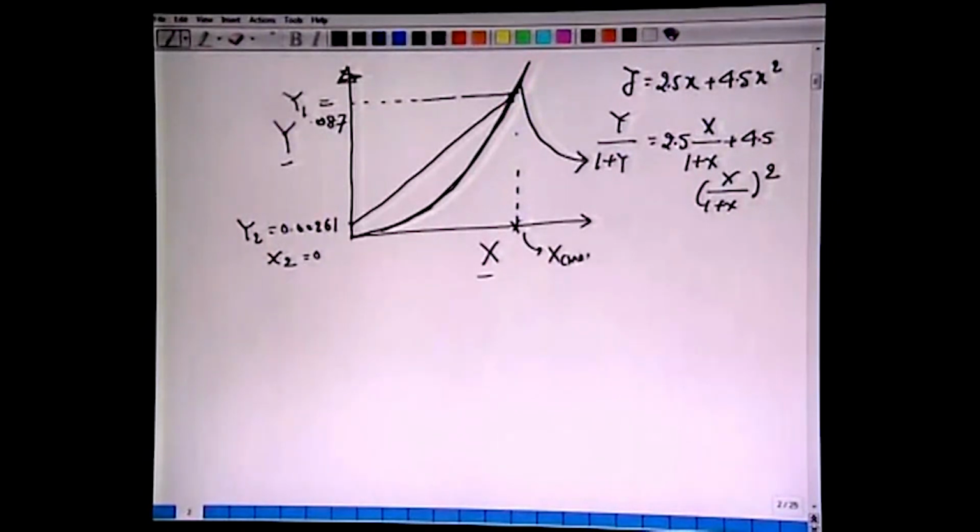This is the maximum, with LS by GS. This gives the highest concentration we can have in the spent liquor, corresponding to this minimum LS by GS flow rate. This X max from the graph turns out to be around 0.31.